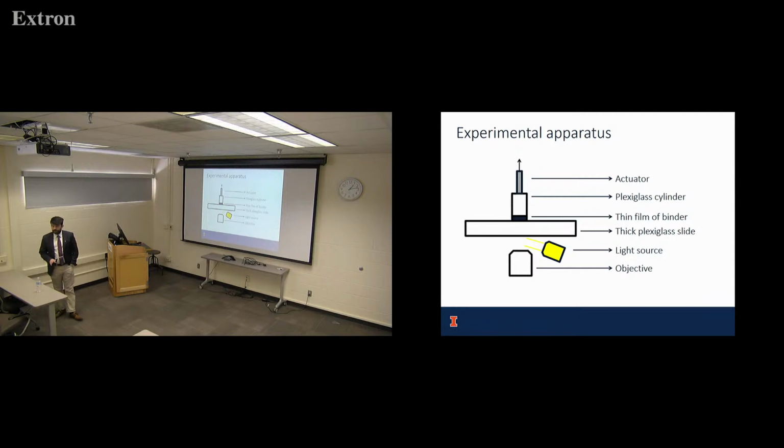Yeah, this is a very good point. There is no way to say that this is for sure going to predict mixture cracking. Probably that's a big reason we don't see perfect correlation with the mixture, because much of the mixture cracking is an adhesive problem rather than cohesive. So for this one, we are thinking of developing a test for binder screening, maybe before you've even chosen the materials for the mix.